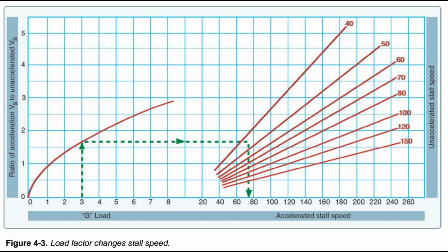Weight and balance. Compliance with the weight and balance limits of any aircraft is critical to flight safety. Operating above the maximum weight limitation compromises the structural integrity of an aircraft and adversely affects its performance. Operation with the center of gravity, CG, outside the approved limits results in control difficulty. The aircraft's weight and balance data is important information for a pilot that must be frequently re-evaluated.